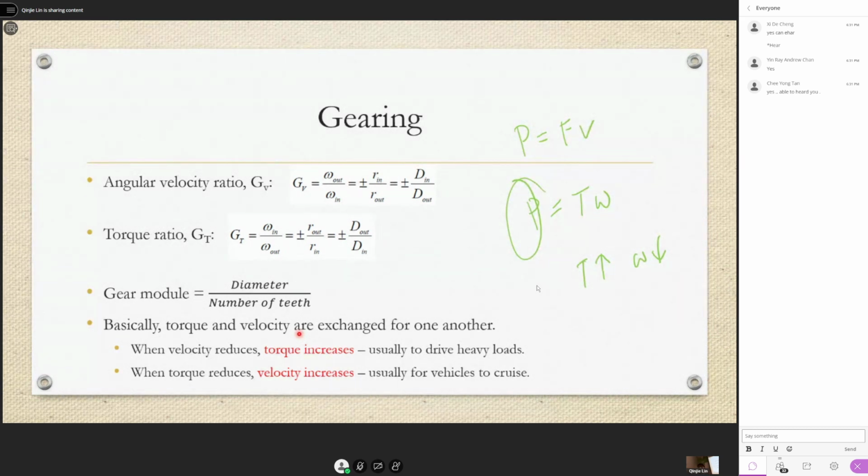Your wheel speed increases, so your smaller gear speed also must increase to match. But why can we not do that? Because the engine is not designed for the gear to rotate so fast. The engine cannot possibly exceed a certain amount. Let's say it can only run at max 6,000 RPM. For the wheel speed to increase, the first gear would have to go to 7,000, 8,000, but it cannot.